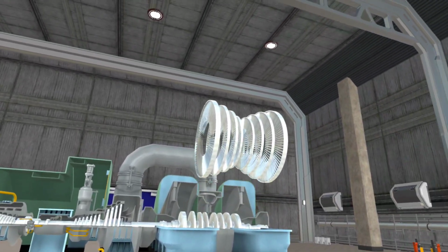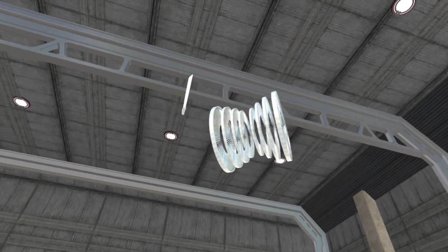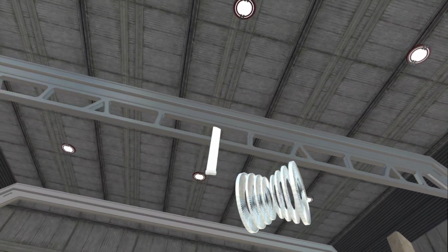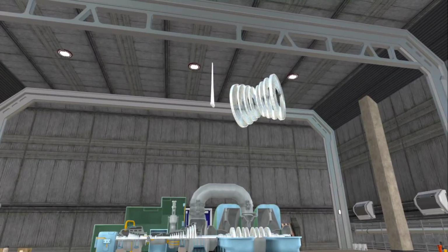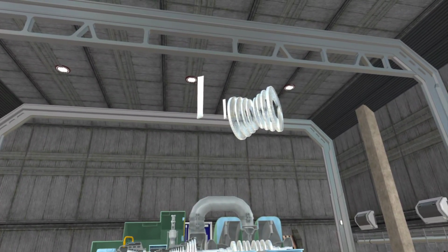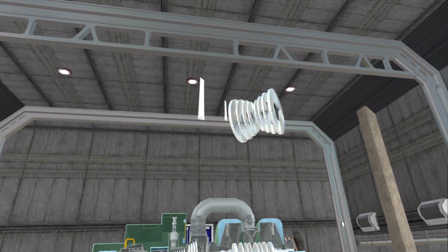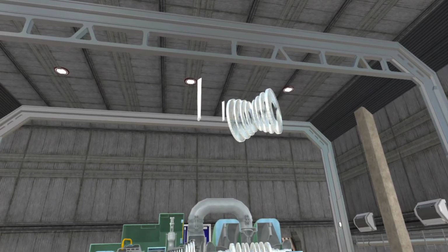The efficiency of a steam turbine depends mostly on the design of the blades. The blade has an airfoil shape that creates a rotary force to rotate the turbine when the high-energy steam passes through it. Here you can see how long the last stage turbine blades are as compared to the first stage blades. The tip of these blades will have a very high velocity as compared to the velocity at the root.